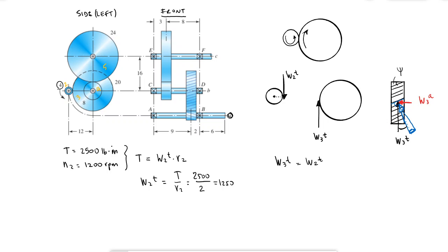Now I know that these values are diameters. I'm gonna make them very clear, using green: 4, 8, 20, 24. I know that those are diameters because this 16 would result from adding half of 24, which is 12, and half of 8, which is 4.